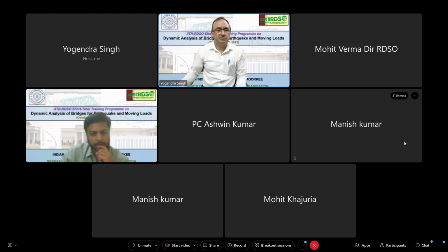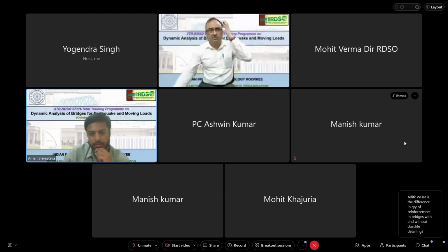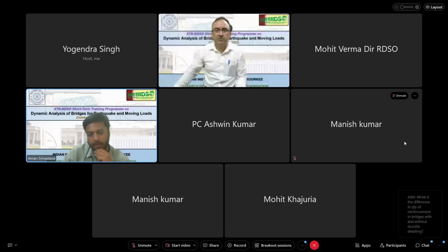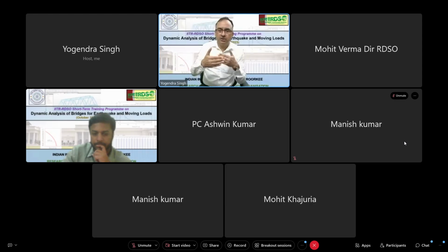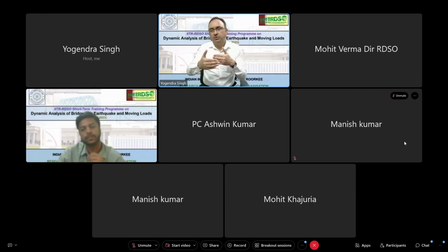Okay. Mr. Sudeep wants to ask how to model shear key, means pounding or arrestor, means to account for the pounding action of the superstructure, how to model a stopper or arrestor. Okay. So when we are modeling the stoppers or other types of devices which are based on impact, there are two issues. One issue is the high stiffness of the shear key or this stopper, because it is small and stocky, so it is having very high stiffness.